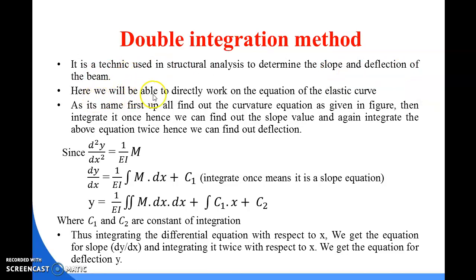Here, we work directly on the equation of the elastic curve. First find the curvature equation as given in the figure, then integrate it once. Hence we can find the slope value, and integrating again, we get our deflection value.